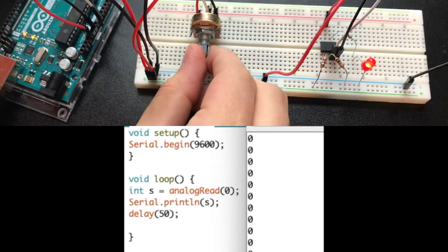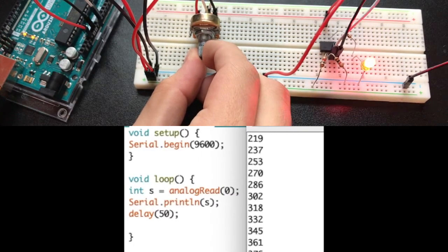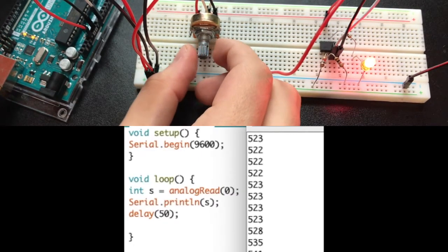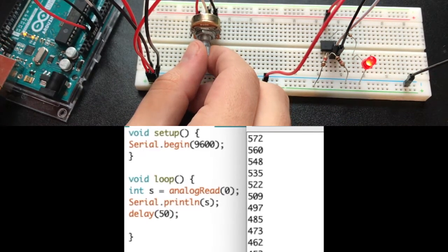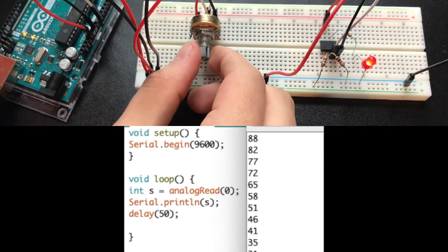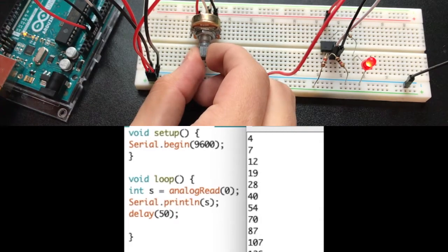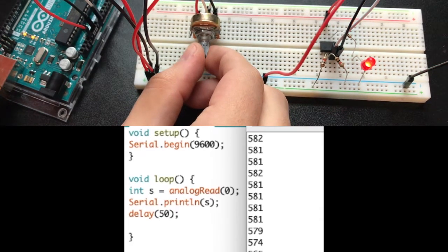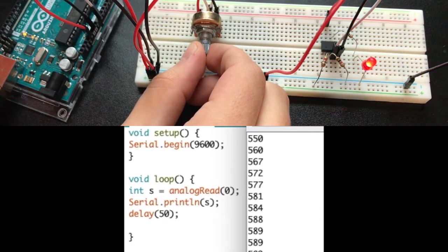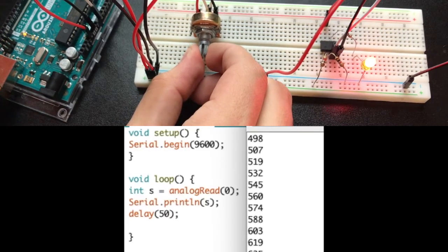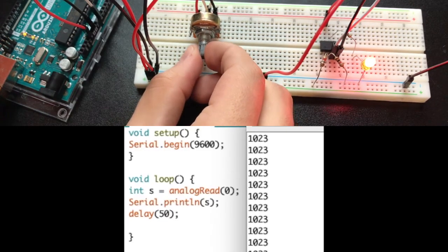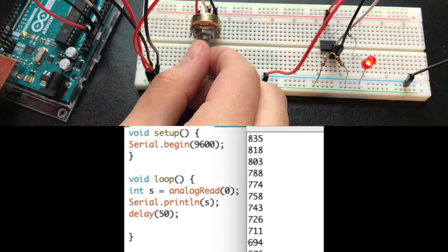As we can see from the graph provided in the lab, once our potentiometer input is greater than the 2.5 volts, the Vout will be set to the 5 volts, which is supplied to the op-amp. And when the potentiometer input is lower than the 2.5 volts, the Vout is much less, thus a less intense LED.